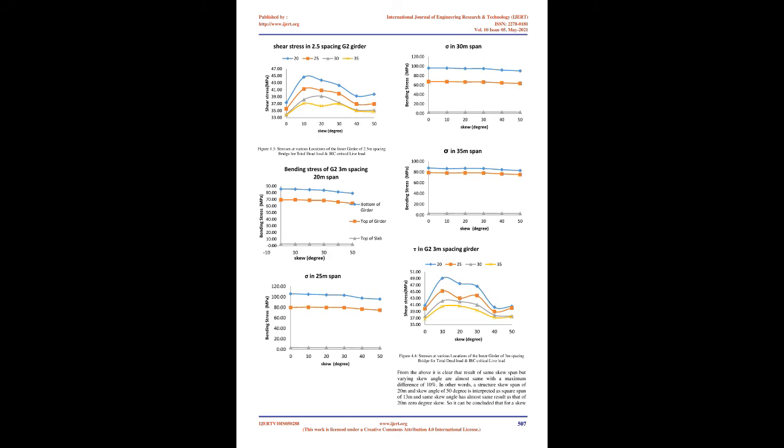The positioning of the vehicle is an important factor from a design point of view. The most critical position, both in longitudinal and transverse direction, on the deck will be one that results in the maximum value of moment and shear in the respective direction. The longitudinal placement of loading should yield maximum bending moment along the span, while transverse placement should give maximum moment in that section. In the same way, transverse and longitudinal placement of load is adjusted to get maximum shear in webs.